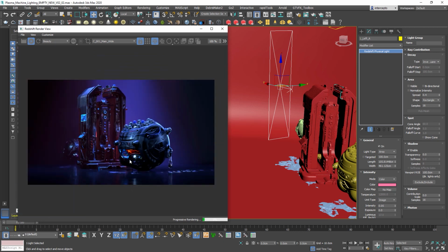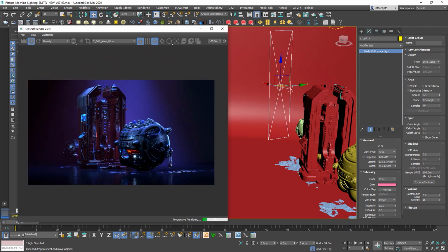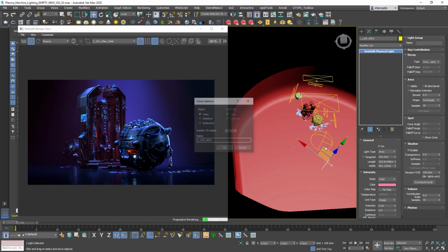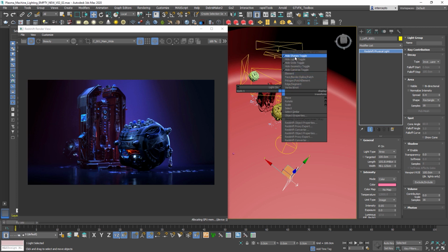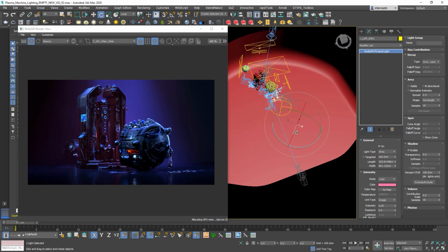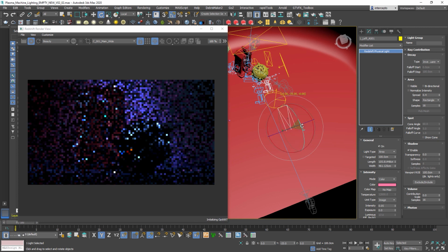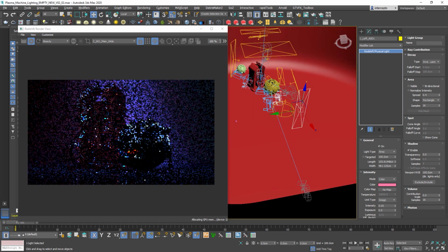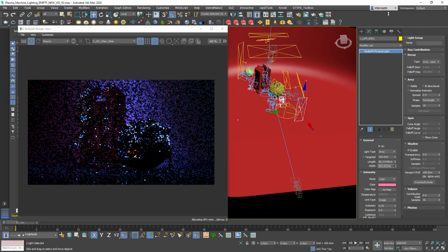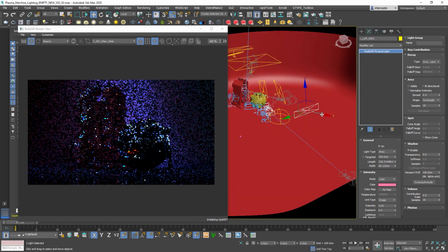What I'm missing right now is something to separate that sphere a little bit more from the background. Actually, to unify it a little bit. So what I'll do is I'll use one light that's closer to where the camera is. And if I turn camera on, that's my main camera. And then I'll put it somewhere over here. Let's set rotation to be aligned to floor first, and then I'll do 90 degrees rotation. And if I scale it so it's much wider and at a certain angle, let's see how that's gonna work.